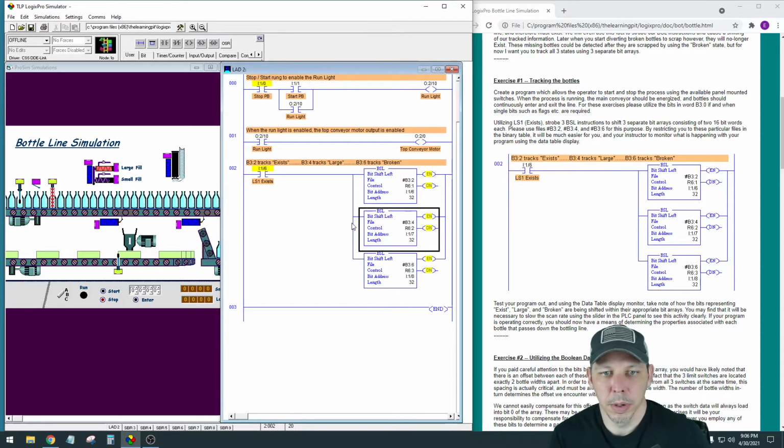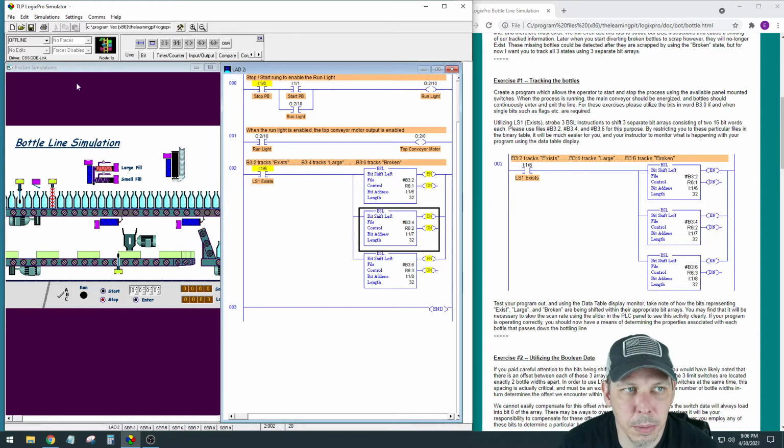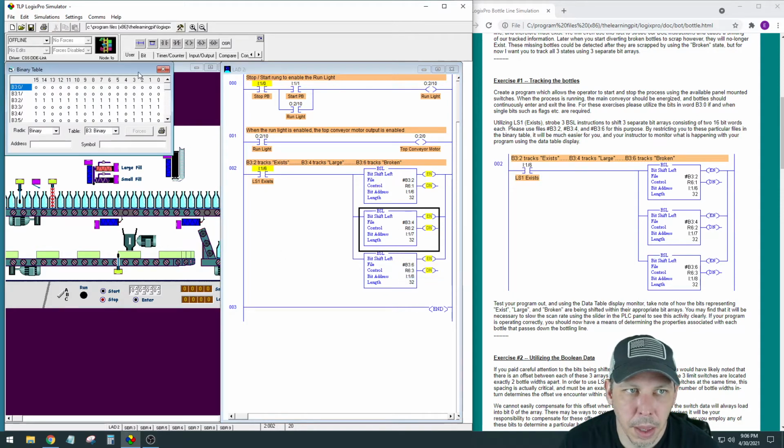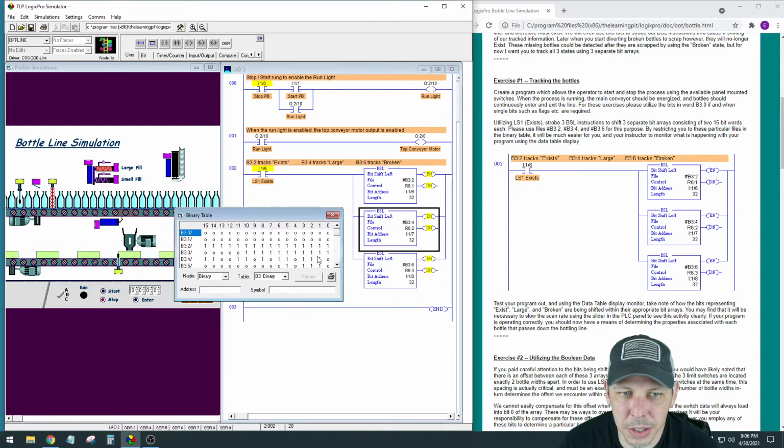Another pro tip here is a lot of the times when you reset the simulation and you clear the data out, it'll reset these lengths to 0. So if you go in here and you look at your data table and you see that nothing's changing, it's not updating these, and it was before, your lengths probably got reset to 0. You didn't type them in there, but there's one of the resets that you can do on the simulation part that'll zero these all out automatically, and then you download it and run it and you don't understand why these aren't working anymore. Those got reset automatically by the program back to 0. So the length that you're storing the data in is 0 bits long.